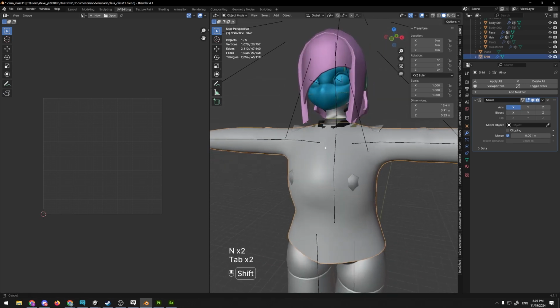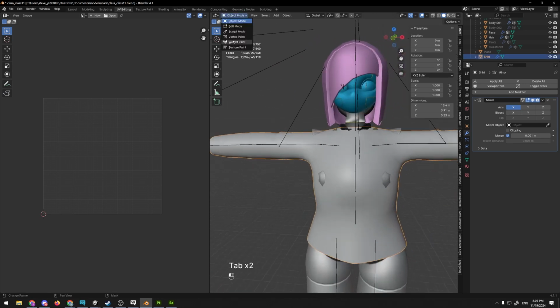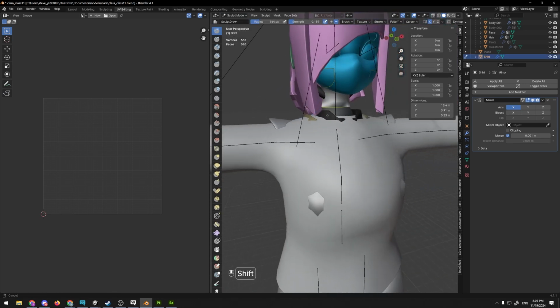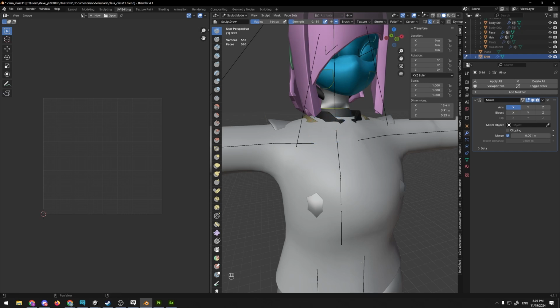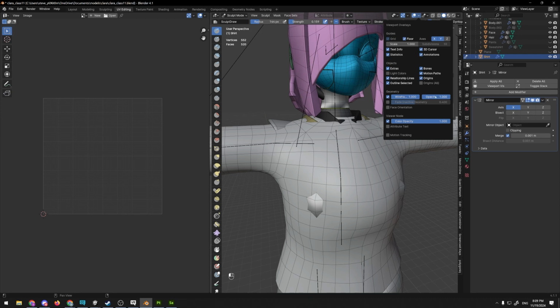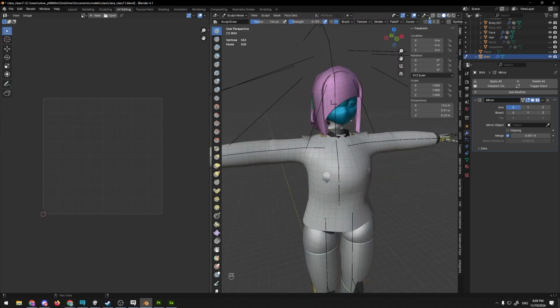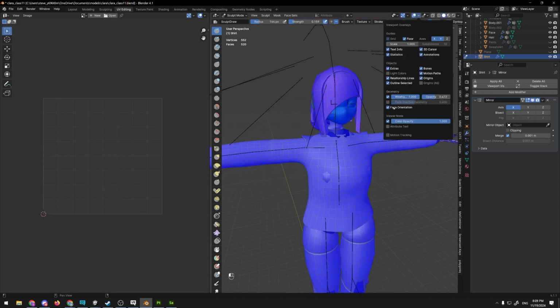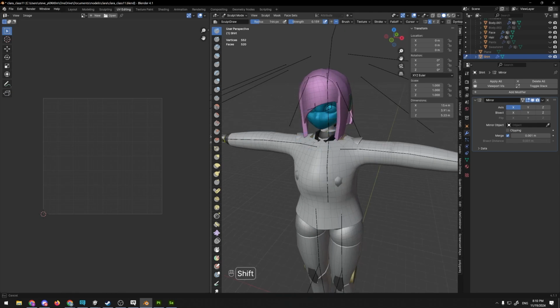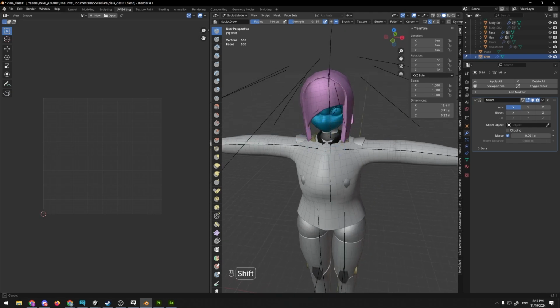So we need to obviously fix some of the clipping here. We can go ahead and go into sculpt mode and start to figure this out. We're going to want to smooth a lot of these verts. Reminder that we go over to the viewport overlays and down to wireframe to be able to see the wireframe while you sculpt. And I think there might have been some issue here with our face orientation. Nope, that's good. Cool. You can Shift-click and hold in your sculpt mode to smooth.